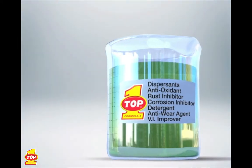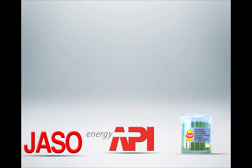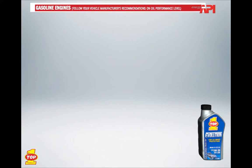There are 2 main governing additive regulator entities that are used when manufacturing motor oil: API, the American Petroleum Institute, and JASO, the Japanese Automobile Standards Organization. API developed a classification system to identify oils formulated to meet the operating requirements of various engines for cars and trucks. There are 2 types of API categories, S and C.